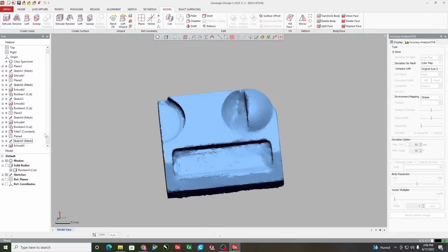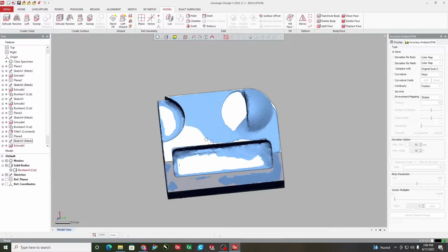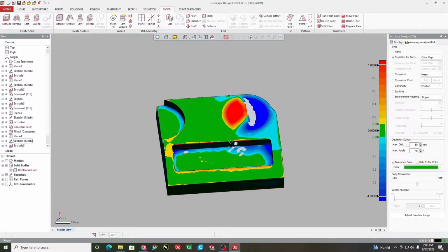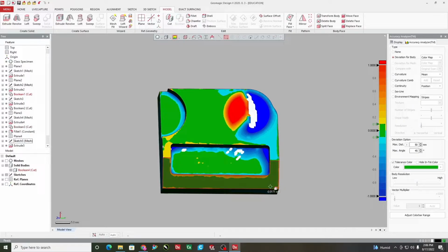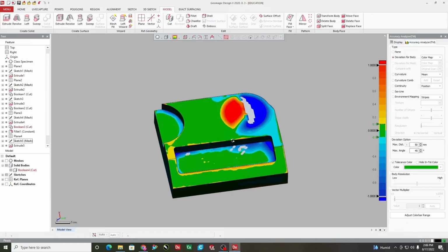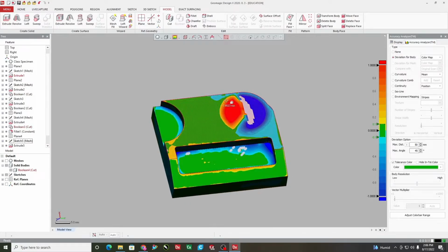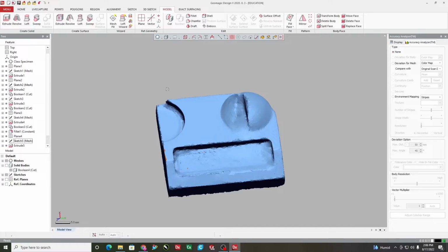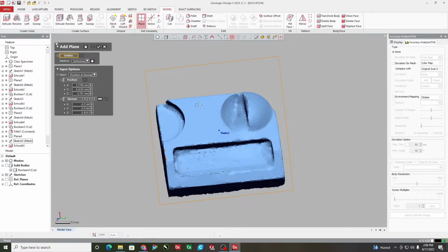Now, this is the mesh body that we have got. Mesh body means it's the captured data that we have got from the scanner. So, the CAD model now is when it is projected over it. So, we can see the maximum part is green, it is close to what we have got in the data. So, now only the red portion and the blue portion is left, that is the dome. So, this is my base object.